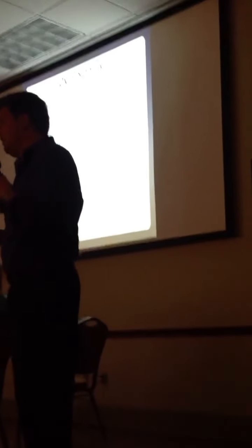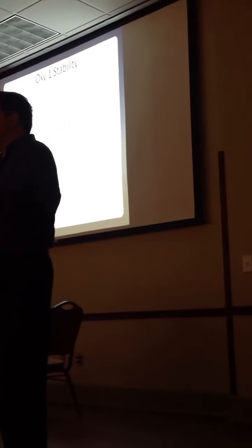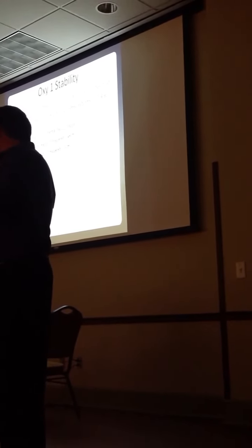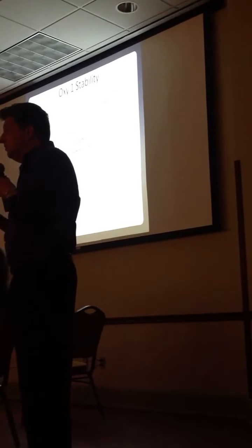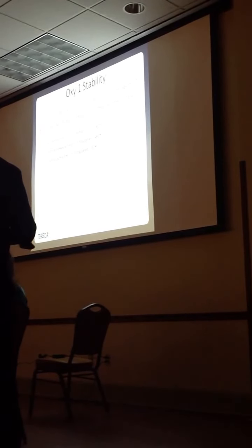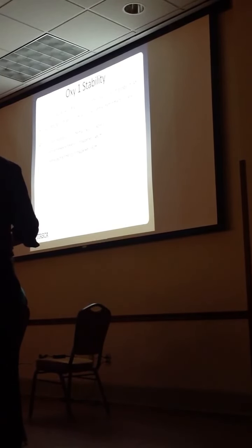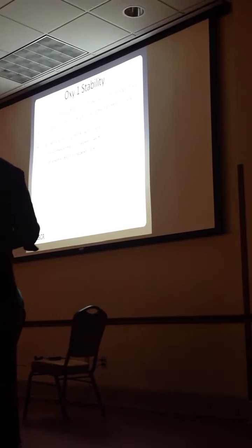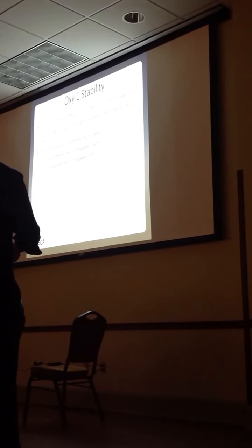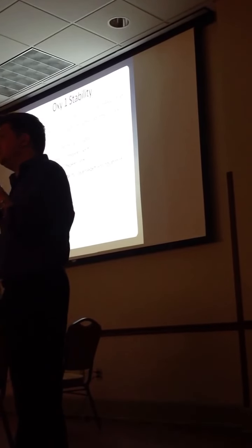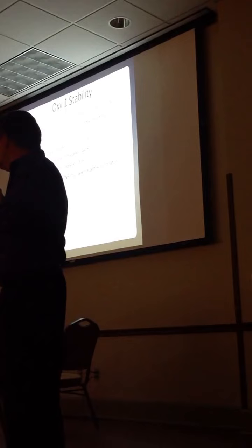The first thing we've done is taken what we know about the cavern and tried to predict what the sinkhole would look like if it were to fail. I'm not saying that it will, I'm saying that if it did, what is that sinkhole going to look like? Because we need that to make plans, as the governor was saying today. The initial sinkhole analysis suggests that if it did happen, the sinkhole diameter is about 460 feet, and the sinkhole depth estimation is about 80 feet. And we're fairly confident with this because we've done the same analysis on the current sinkhole, and we're about right.